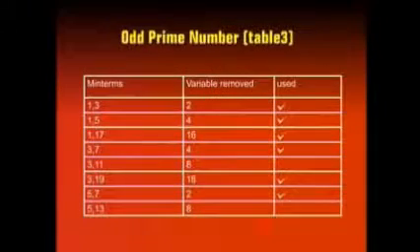The results of the comparisons between 2 minterms are represented in a separate table referred to as table 3. The first column lists the minterms that have been compared together to eliminate common variables. So terms 1 and 3 form a single term eliminating variable d.